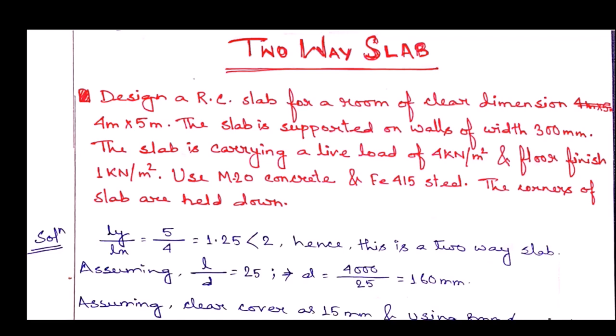and for both sides, that means for longer span and shorter span, we have to design reinforcement for middle strip only, and for 4 edges we have to provide edge strip as per IS 456:2000. The total consideration of two-way slab is given in Annex D of IS 456:2000.